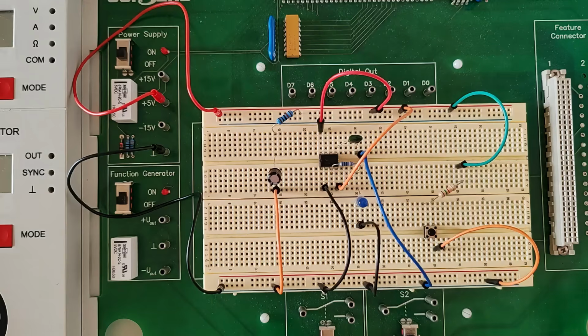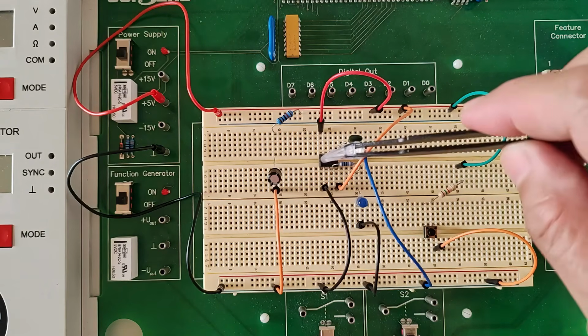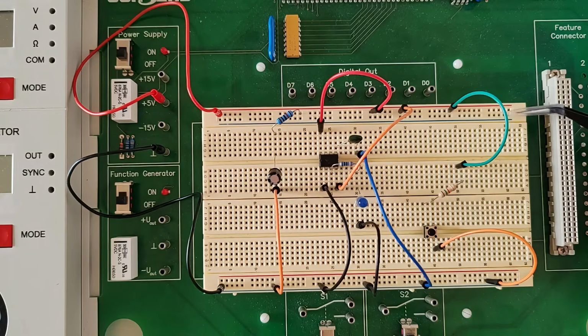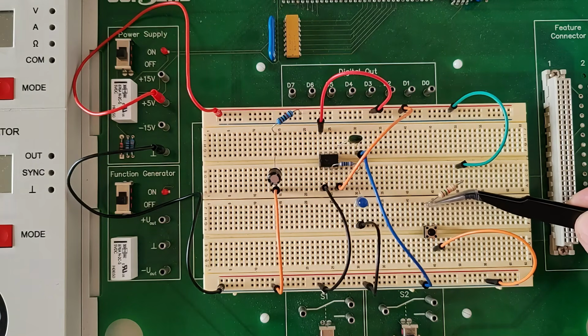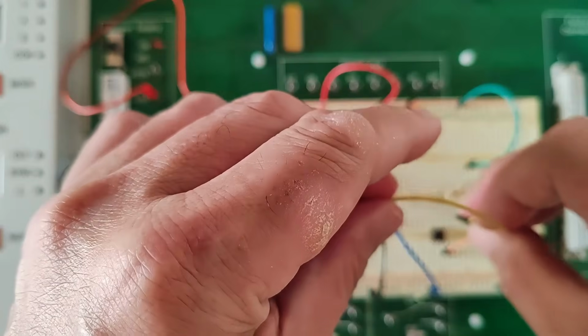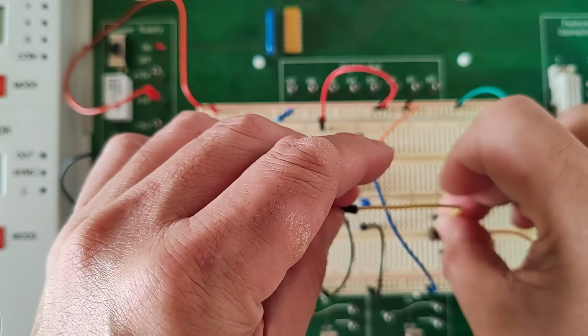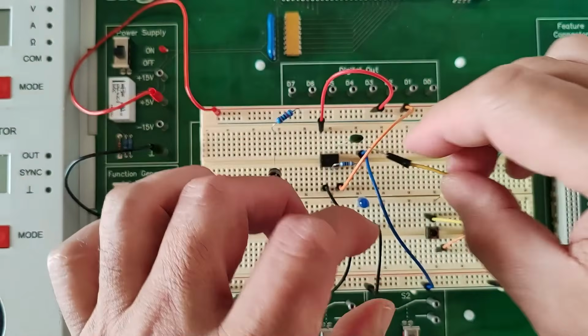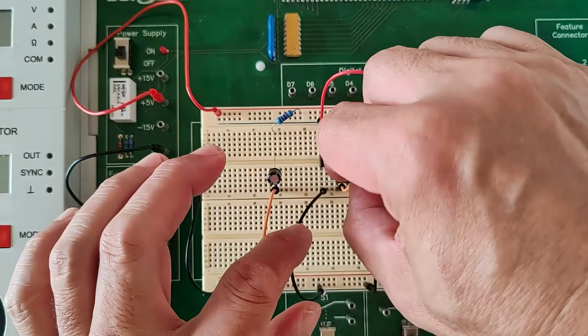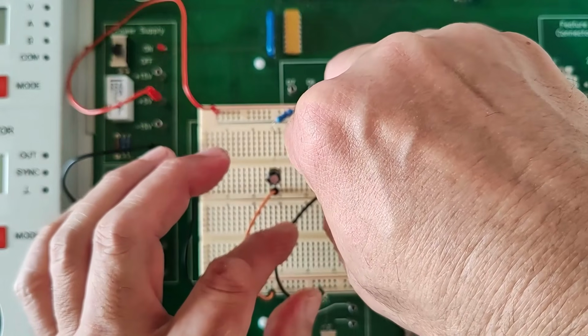Now, the connection between this section of that circuit to the NE555 is through the trigger pin, because this is our triggering mechanism for our monostable multivibrator. The push button switch here and this 1.5 kilo ohm resistor. So I need to connect this junction between the 1.5 kilo ohm resistor and the push button switch to pin number 2 of our monostable multivibrator circuit. So let me just do that. Pin number 2 of the 555 timer will have to be connected in this junction. Let me do that now. Pin number 2.